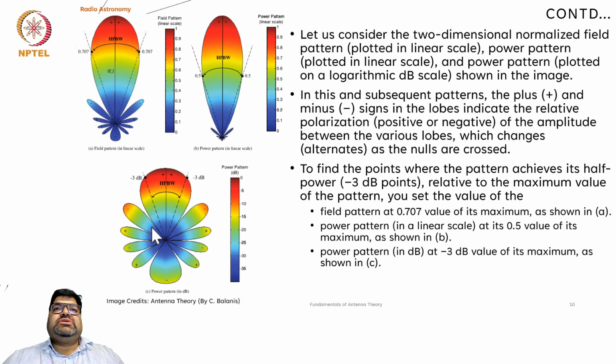Okay, the efficiency goes down. We already have very faint signals coming from the sky. If they are further reduced because of the inefficiency of the antenna, that is not desirable. So we try to concentrate on the region where the antenna is most sensitive. An antenna is most sensitive within this HPBW region. Of course, we have sensitivity towards this first null. We will come to this a little bit later, but the efficiency becomes much lower. So that's one thing to remember, and this HPBW forms our field of view for a particular antenna.